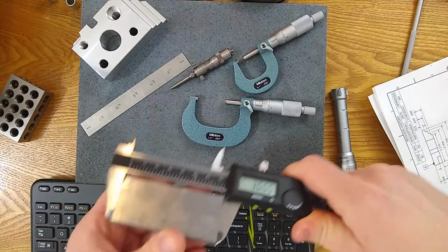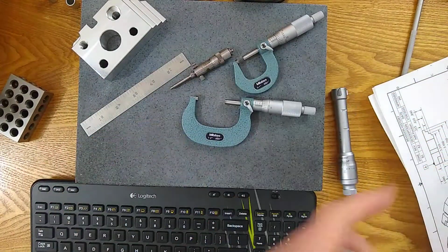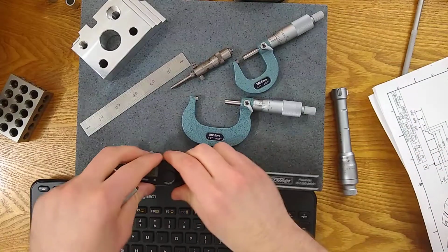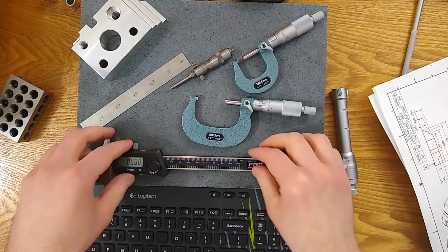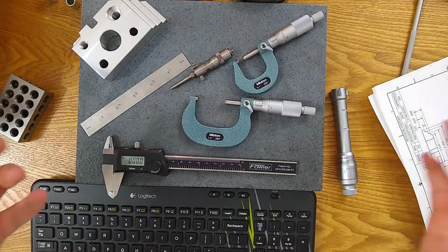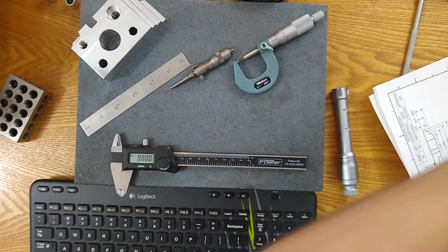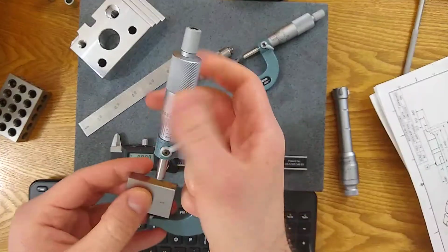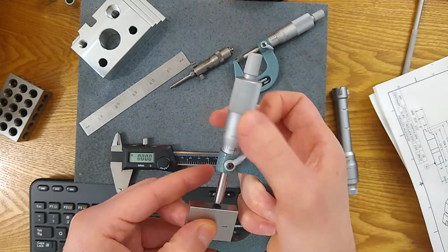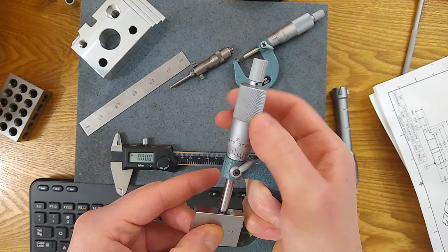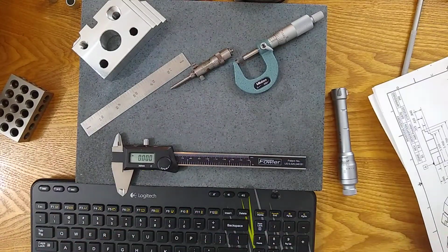With this camera, I don't know if you can see on the front, but on the secondary camera, I was getting 3 inches, or 2.999 when I had a little bit bad angle, but that's what they're saying. So whether I use a caliper, whether I use a micrometer on a 1-inch block, it's going to be the same thing. They're going to say we're going to be within the accuracy that we state in our catalog. That's kind of our guarantee for how accurate, comparing to a known standard.